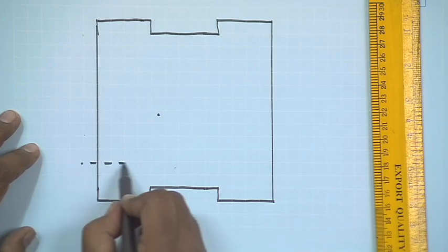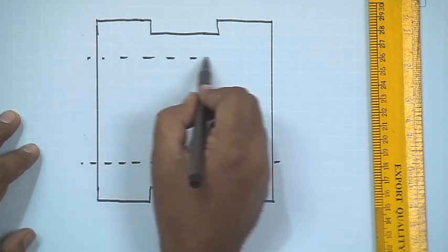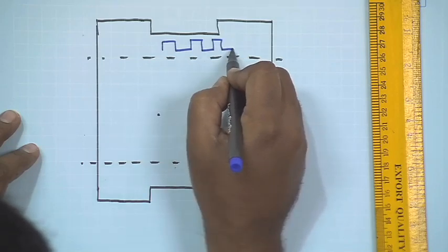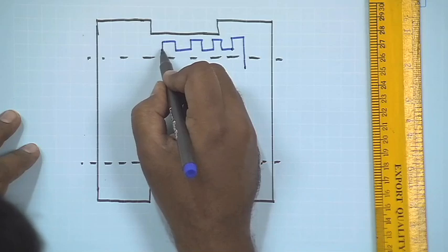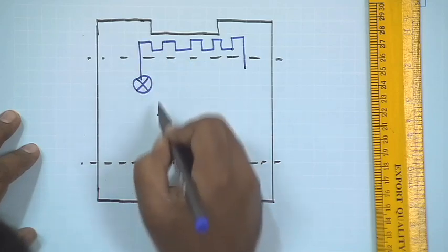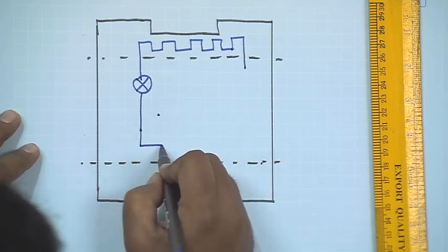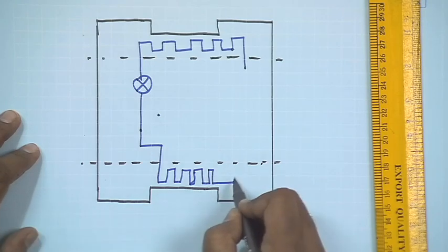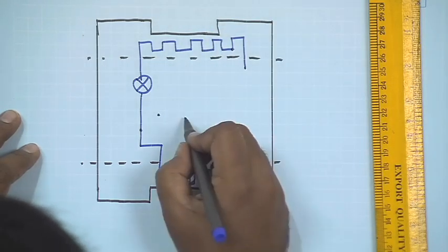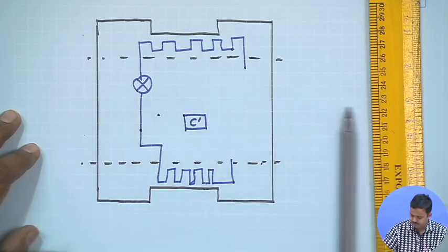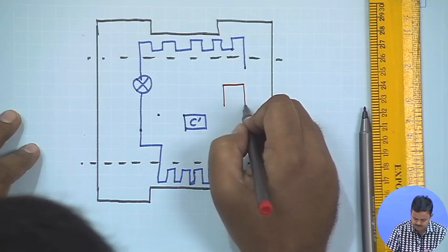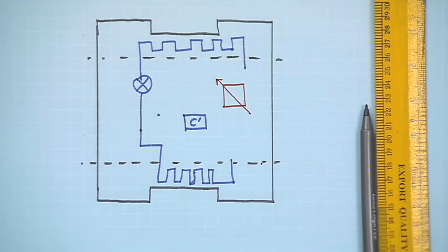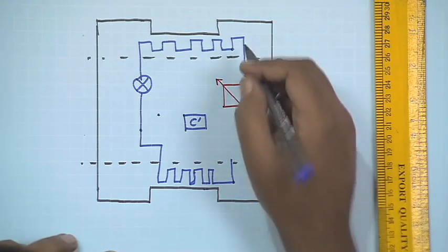So, it is the same thing now. This is during winter. Let me draw the same. The expansion valve comes out, and it goes up like this. I have the compressor over here again, C prime, and I have the 4-way switch also over here, but in this case now the position of the switch is changed. So, if the position of the switch is changed, this is what happens to the flow stream.